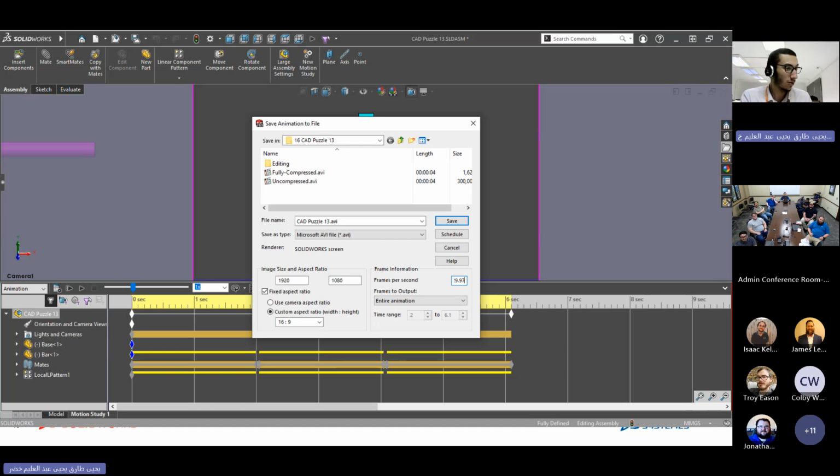So the animation would play better inside of SolidWorks than it would play inside of your video player, which makes no sense. But from my experience, 30 sounds like the sweet spot. Unless you actually have a lot of motion happening very quickly, in that case, you would go with the 60 value. The only cases that I encountered was the image I showed you earlier, where I had these balls falling down. To capture all of these quick differences, I had to go with 60 frames per second. But other than that, 30, sweet spot, not big file sizes, nothing. It's perfect.